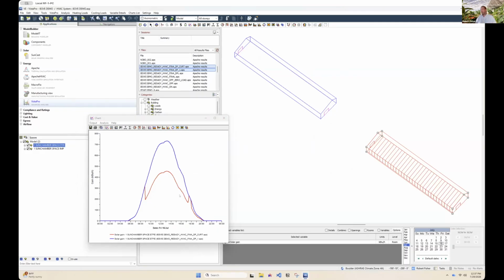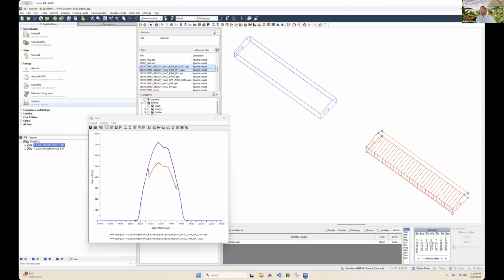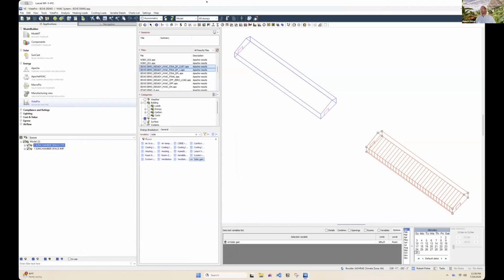But once those properties are in there, you can then reduce your actual HVAC loads theoretically according to where you're at in the world, because our actual main load we battle is that solar load coming in. And I think that's very apparent that almost any and every day you're looking at here, we are getting a solar reduction in BTUs. Now, if we go to January, it's not as much always, but it's still occurring on most days. We are clipping the sun and preventing that energy from getting into the building. And then we do not have to remove the energy from the building if we prevent that from occurring.